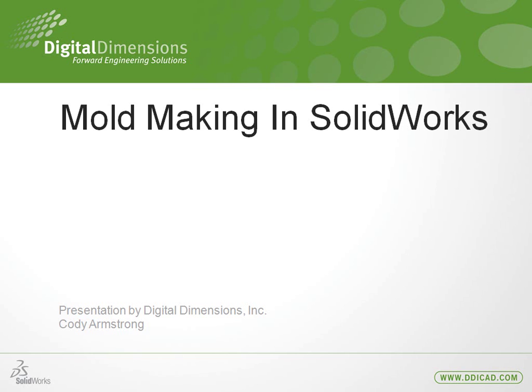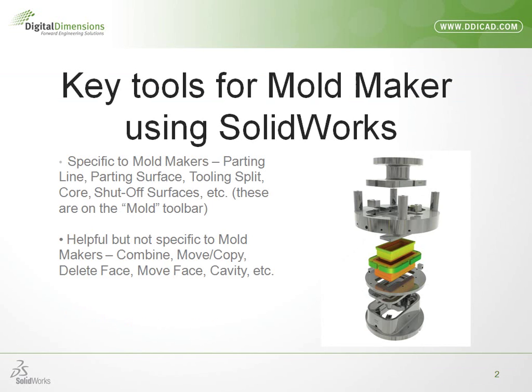My name is Cody Armstrong, and today we'll be going over mold making in SOLIDWORKS. SOLIDWORKS offers a lot of very specific mold making tools. Some of the tools that come to mind on the mold tools toolbar are parting line, parting surface, tooling split, core, shutoff surfaces. A lot of these tools are heavily automated specifically for mold makers to create the mold as quickly